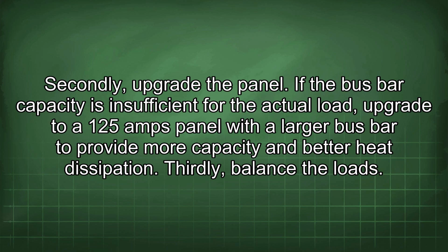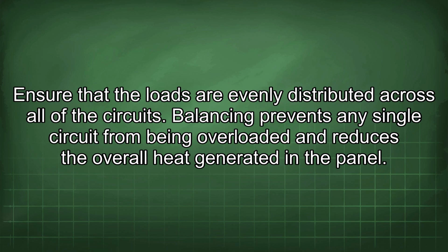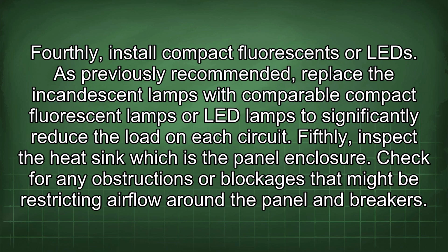Thirdly, balance the loads. Ensure that the loads are evenly distributed across all of the circuits. Balancing prevents any single circuit from being overloaded and reduces the overall heat generated in the panel. Fourthly, install compact fluorescents or LED. As previously recommended, replace the incandescent lamps with comparable compact fluorescent lamps or LED lamps to significantly reduce the load